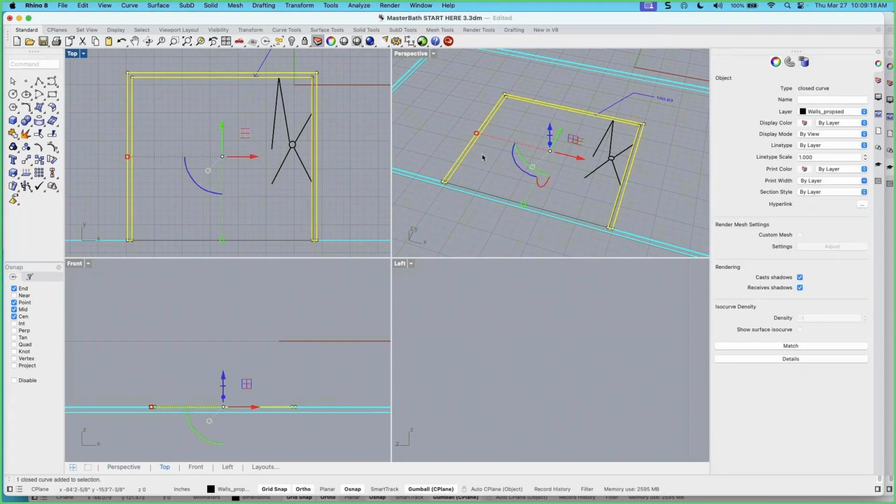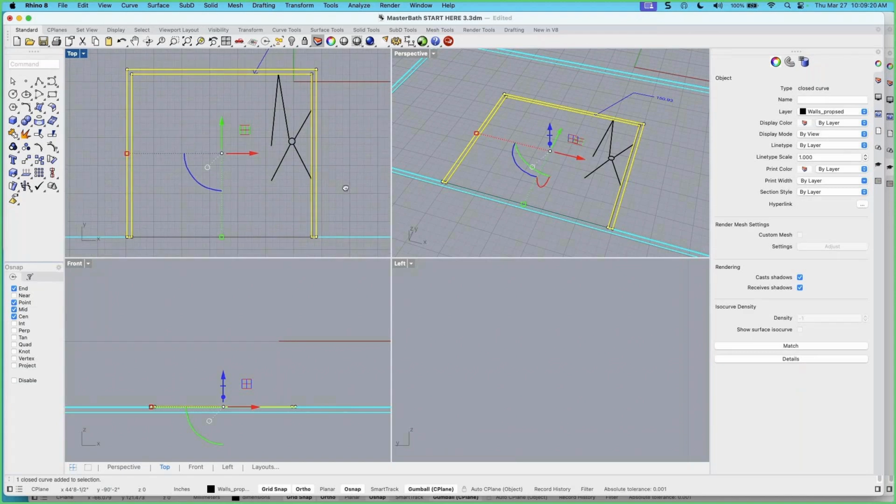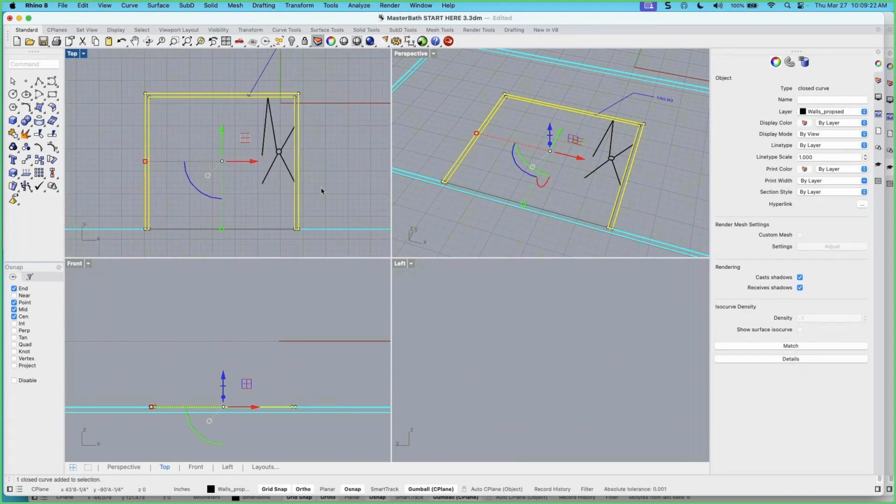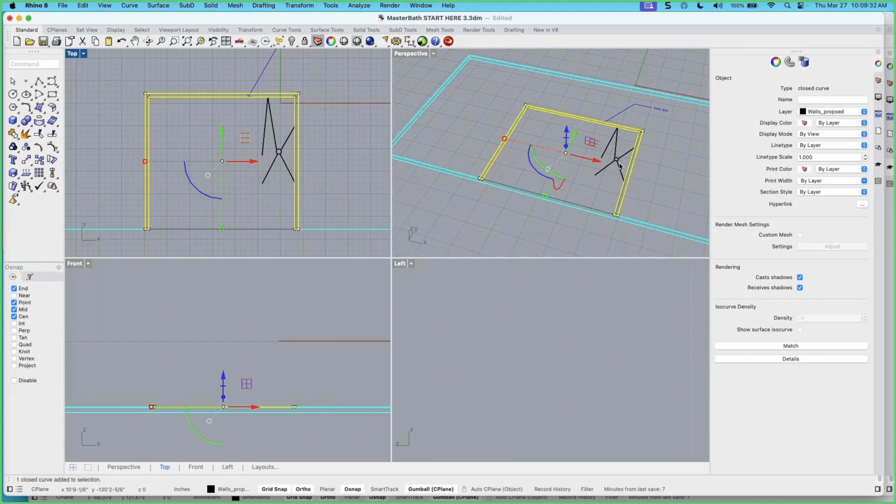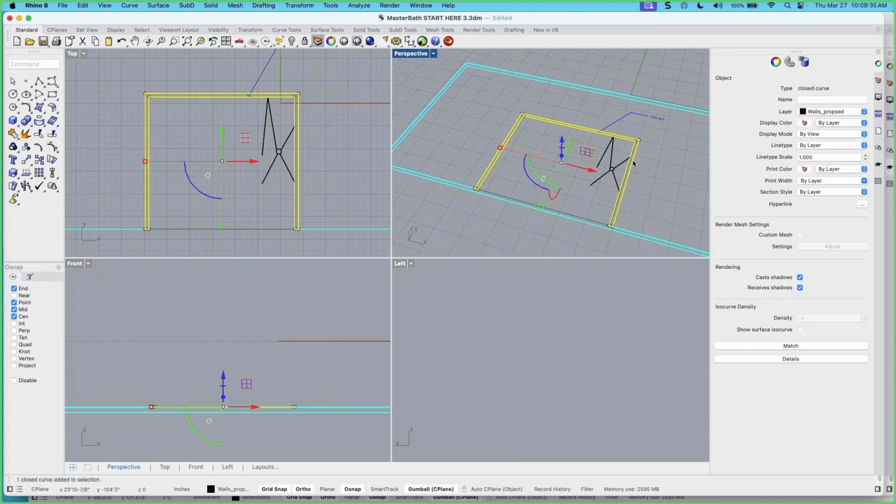When we do an extrusion here, we'll extrude into a closed polysurface. And a lot of times we get the question, when I do an extrude from the Solid menu, why isn't my geometry closed? And there's two conditions that have to be true here, closed and planar. If it's not planar, it won't be a closed polysurface.